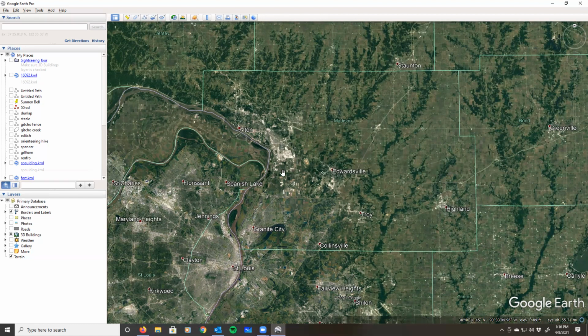The scale factor through the center of the county is probably going to be 1 part in, I don't know, 50,000, too small. So it's going to be much closer to being 1 as a scale factor than what the Illinois West or Illinois East is currently.